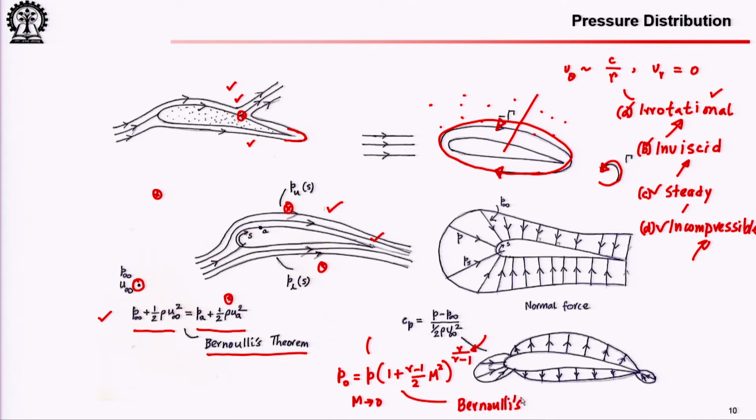So, what we are discussing right now is that you can remember that if these four conditions are satisfied, then Bernoulli's theorem can be applied between any two points in the flow field. We do not have to worry about whether the points are on the same streamline, stream surface, stream tube, etc. But we will see that if your flow field is not irrotational, so if this condition is violated, this will still hold with some restriction. Today we will look at that, because it is important.